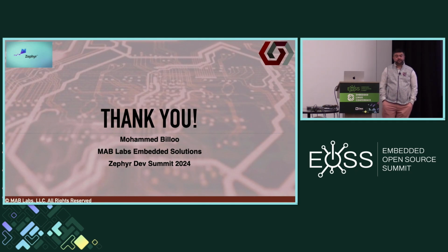Thank you for the talk. If I remember correctly, with STM32MP1, for instance, there were some concerns about OpenAMP and RPMsg throughput from the A7 to the M4. I think someone benchmarked it around 100K per second because it wasn't zero copy. You're always managing this ring of shared buffers in SRAM. So if you want to do zero copy transfers, have there been improvements in how that can be handled in OpenAMP, or is it better to go below that and manage shared memory and signaling yourself?